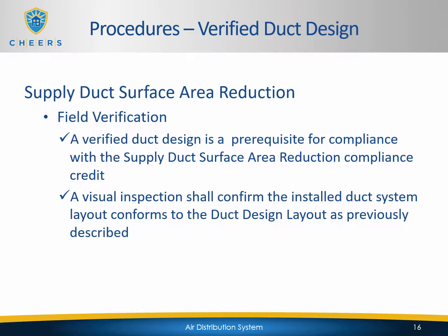Now for supplied duct surface area reduction, the field verification is a verified duct design that it's a prerequisite for compliance with this particular credit, like I just mentioned. A visual inspection shall confirm the installed duct system layout conforms to the duct design layout as previously described.